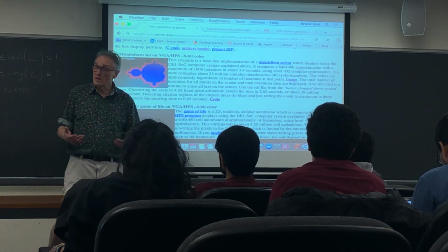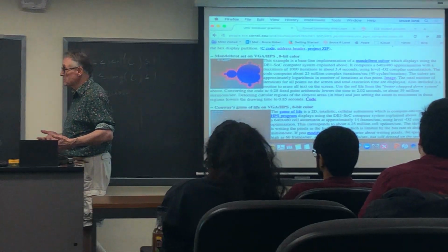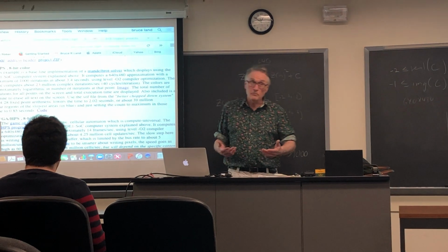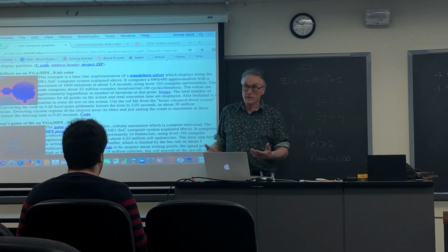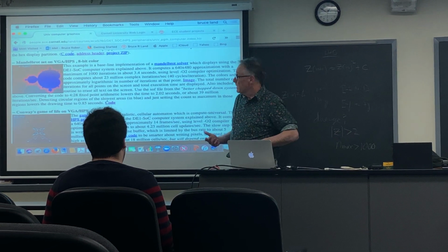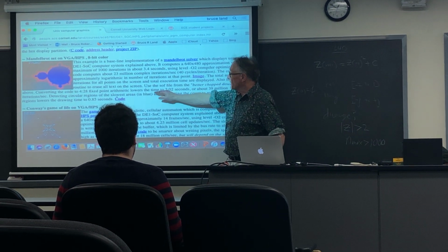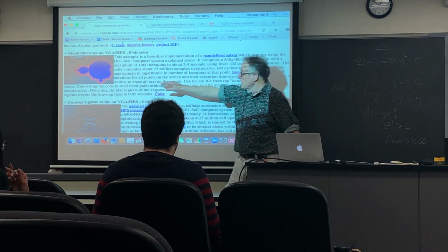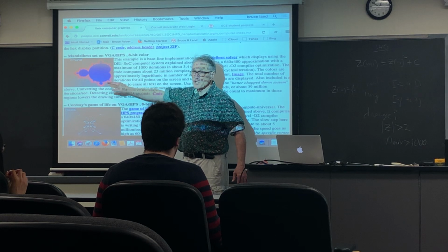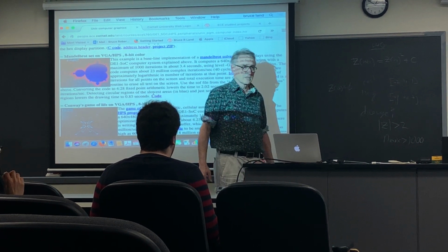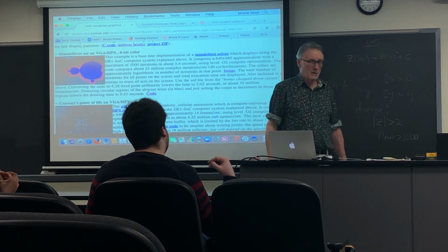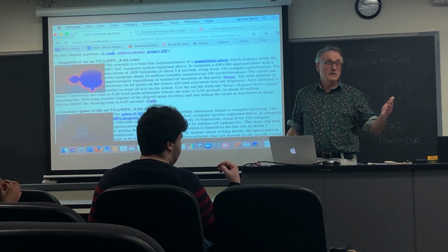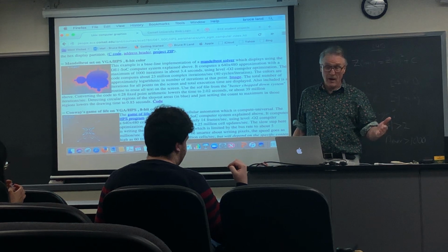So the fewer bits of color depth you can use, the more resolution you can put on the screen. It turns out you can do an 8-bit color image in on-chip memory on the FPGA, but you cannot do a 16-bit image. So I would say 8 bits or less will allow you to be in static on-chip RAM.